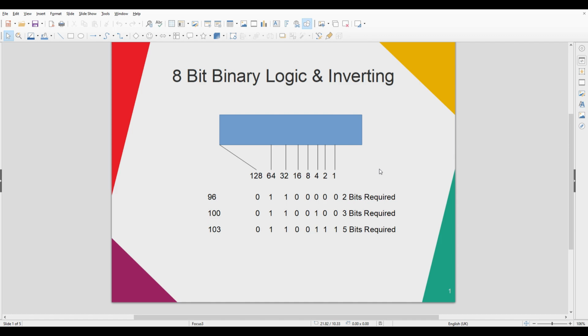In the simulation, I've got both running. I've got the 3-bit running with an AND gate, but I've also got it running with an 8-bit AND gate through NOTing the outputs where they're 0. So they come out as 1 because we know they're already 0. We're not interested in that. We just want to know when our 1s become 1, which is our 64, our 32, and our 4.